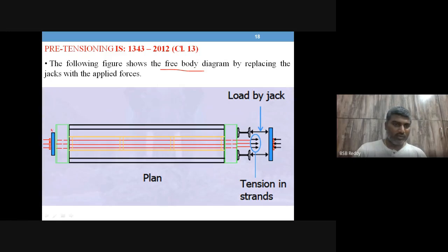So this is one such frame, and you can see that the tendons are being anchored here, and they are being cut at this point after the mold is prepared. This is the location of cut. Okay, so once that is cut, and even at the intermediate locations also we need to cut the tendon so that all three members will be ready.